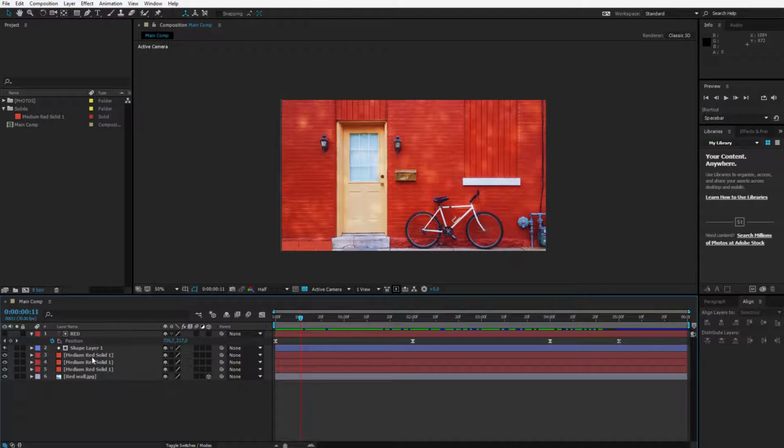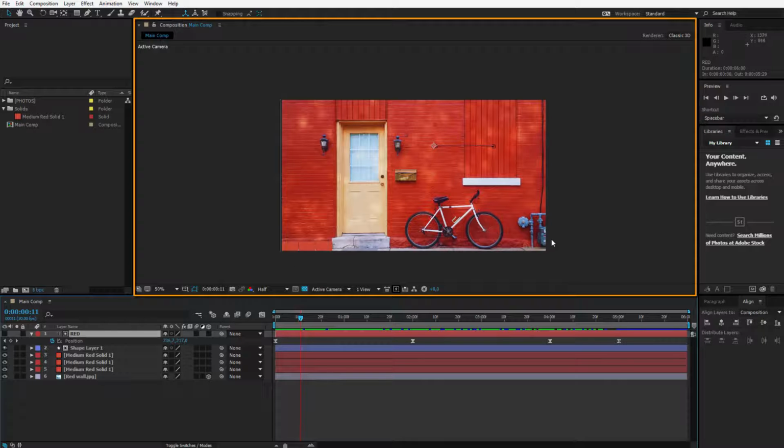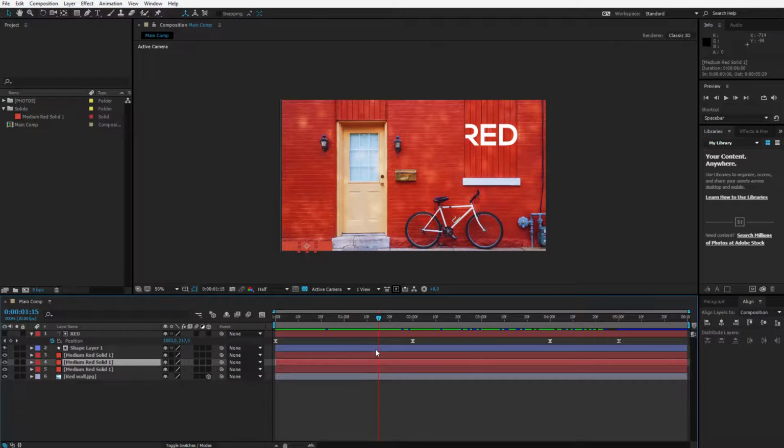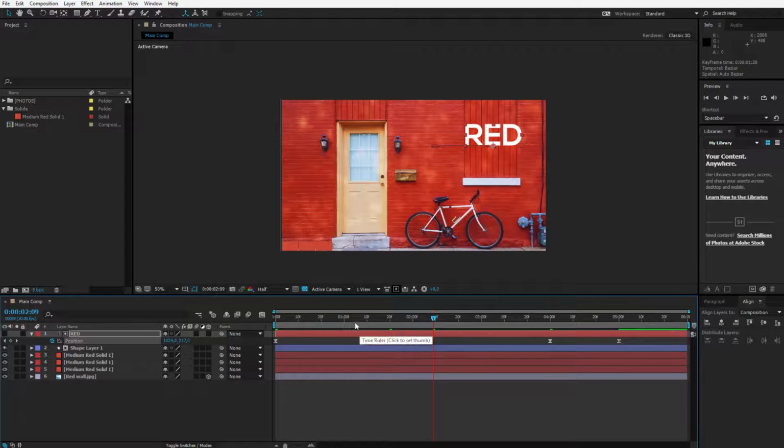Here we have our layers. Once a layer is selected, it will highlight in the composition panel. The composition panel lets us preview what actually is happening on the screen. And a basic workflow in After Effects always looks like that. You import some assets into your project files, you put those assets here as layers, and then you start editing an animation. As you see, it turns green because it has already loaded, and now with the preview panel, I can preview what is happening on the screen. This is used to preview the animation you are creating. If you are not satisfied with the animation, just hit pause by hitting the space bar. You can shift some keyframes to change the animation, and after that it would have to load again. So let me again press on preview.